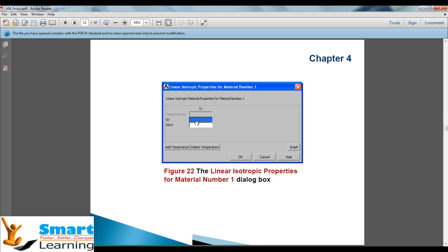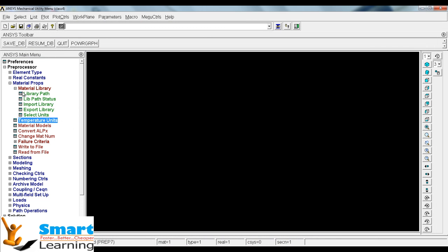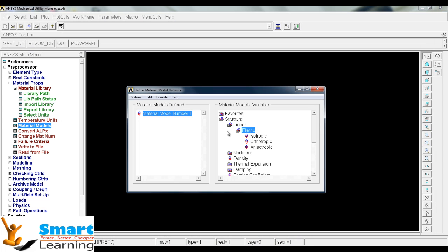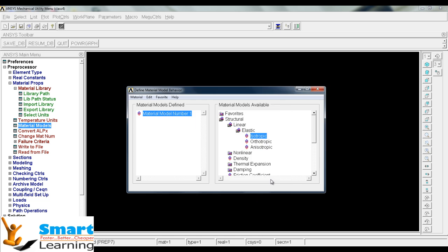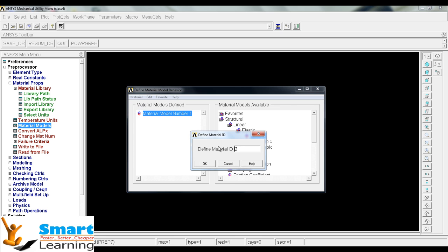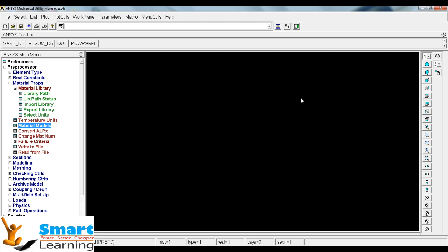You have the Young's modulus and Poisson's ratio when you talk about the material definition. If you go to the material model, elastic, isotropic, you can see the Young's modulus and Poisson's ratio, which are the primary definition parameters you have to set. And here you can see the material number. If you go to a new material, new numbers will be assigned. Based on this material number, you control the characteristics and principles which you define during the project.